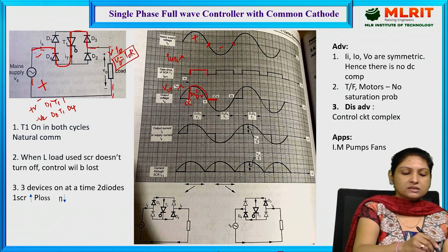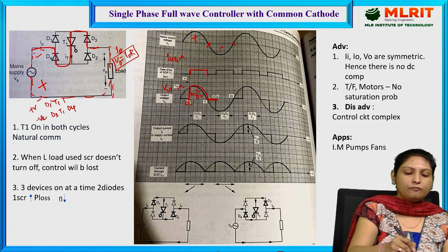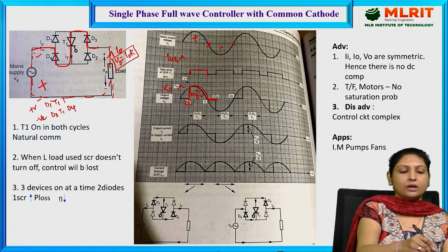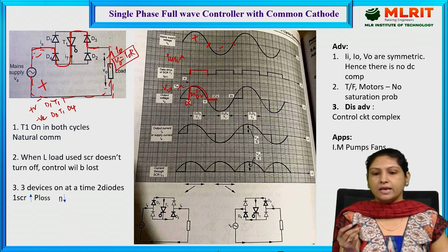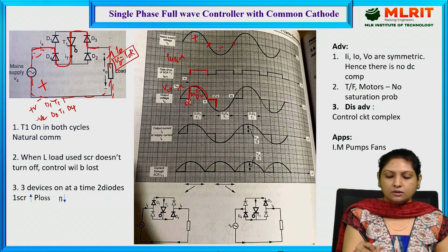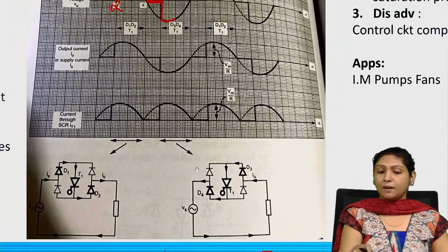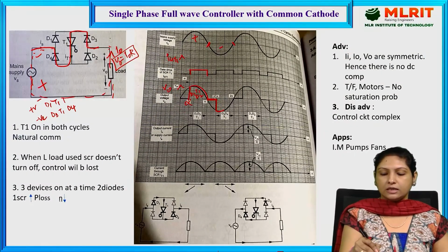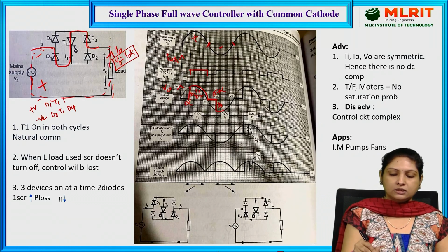So what? It starts conducting current through the load in this direction. Now current is flowing in the upwards direction because of D3, T1 and D4, opposite to that of the first case. That is how we are getting the output as AC, as I told you previously. So now during the negative half cycle, at this instant called pi plus alpha, since we are providing the triggering pulse at pi plus alpha, D3, T1 and D4 are conducting, and it is conducting till 2 pi.